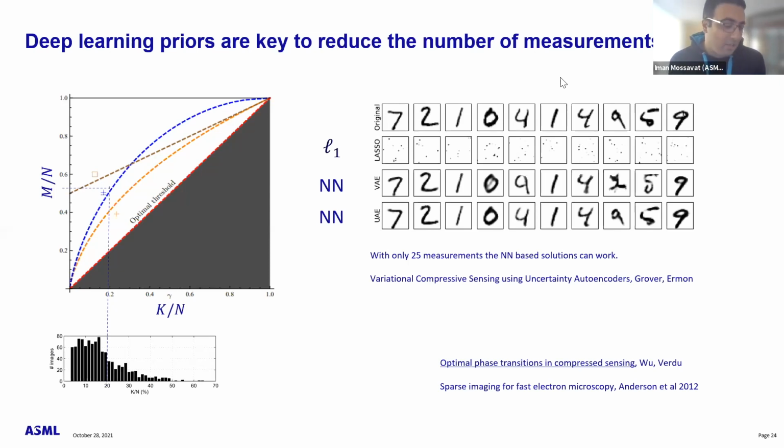Indeed, the classical compressive sensing has some robustness considerations with respect to noise. But if you look at it in the abstract, essentially, compressive sensing is nothing but trading off one parameter with the other. For example, you can make more measurements, trade some temporal resolution, so you take more time to take more measurements and gain spatial resolution, for example, better noise performance.